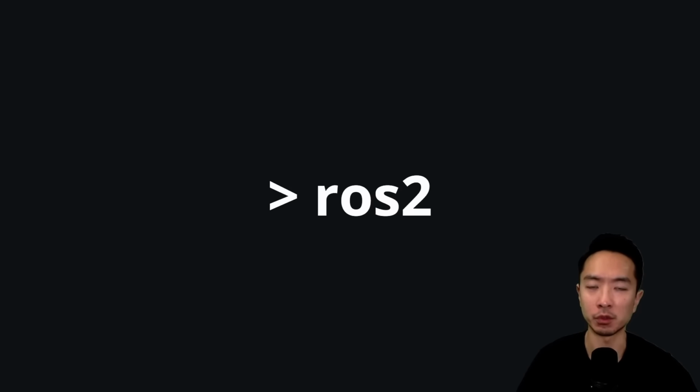So the point of sourcing is so that you let your computer know where the ROS2 installation is located, and that way you can use the ROS2 commands. If you don't do this step, you're going to have to either manually source ROS2 every time, or you could do what I'm about to show you, which is setting it up in some of your configuration file.